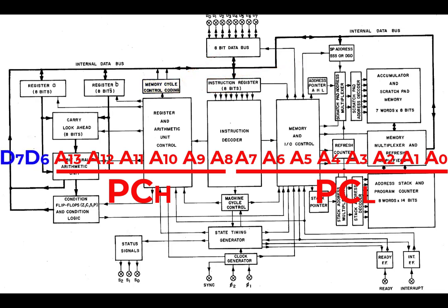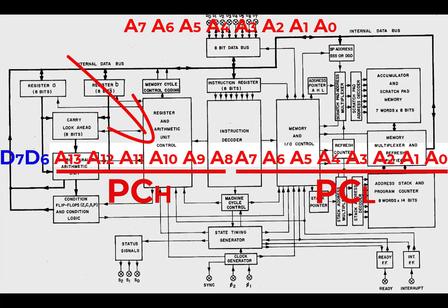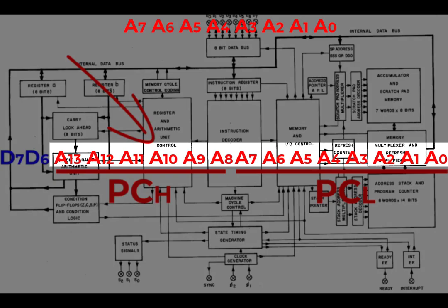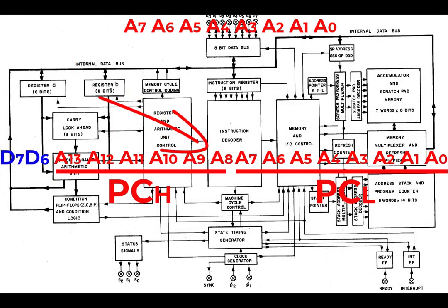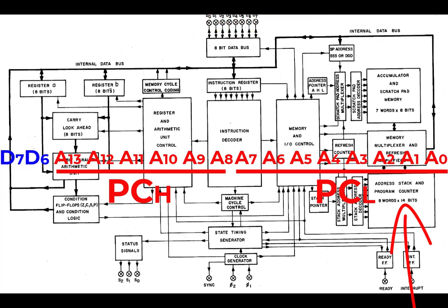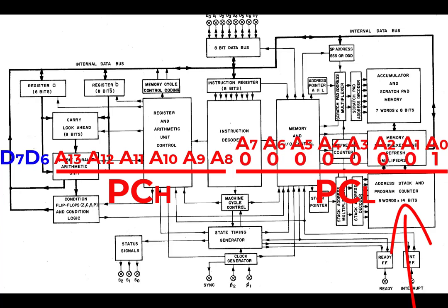In every machine state, or machine instruction, using the new parlance, the first step will be for the processor to put the low address byte of the program counter onto the bus. The program counter, as I hope you understand, is just a bookmark that tells the processor where it's getting its next byte from memory. In the 8008, it's a 14-bit internal register. So in this case, it's putting the low byte of the address of the instruction that needs to be fetched and then executed. After the low byte goes onto the 8008 bus, and the rest of the system hardware deals with it, for example, it latches it onto an address bus to be delivered somewhere else, the low byte of the program counter is incremented.